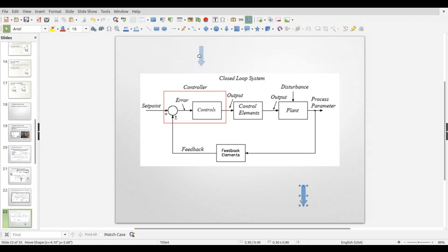All right, so here's again the block diagram of our system. And what I wanted to point out here was that, as I just did on the other slide, this is the summing junction. Now, the summing junction for us is going to be right inside our PLC controller. So we're going to have a set point that we set, which could be inside of the PLC, or once we build an HMI using FactoryTalk or whatever, we're going to put the set point inside the HMI.